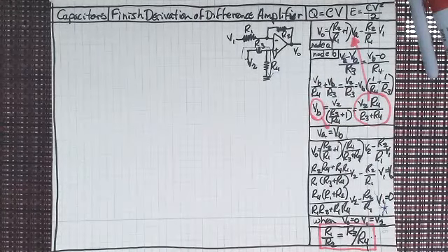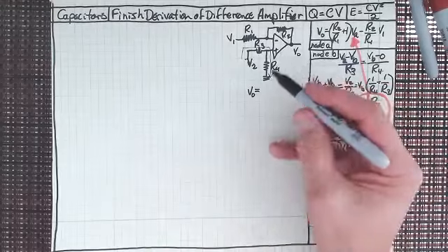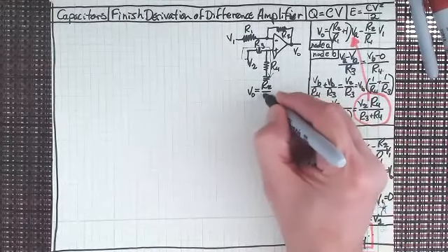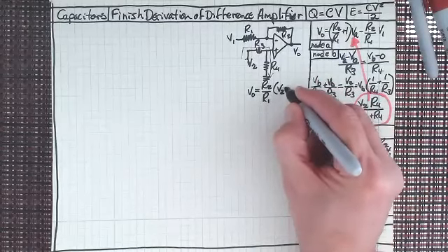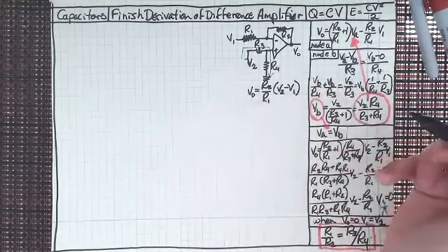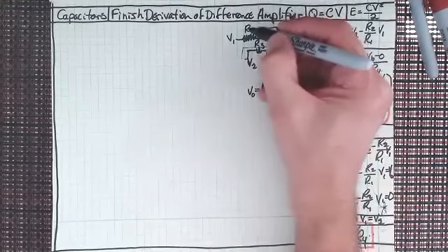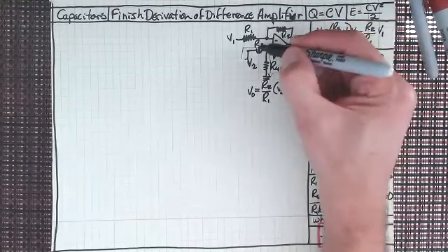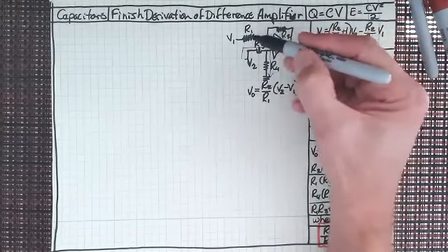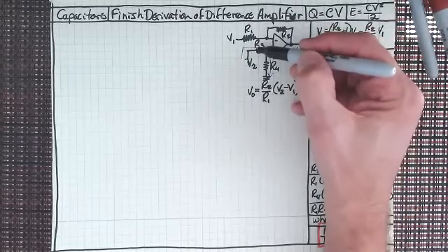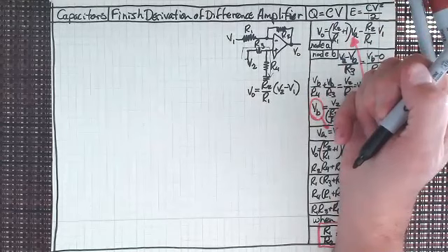Now, what we end up getting out if we use that identity is our equation that says that V out equals R2 over R1 times V2 minus V1, right? Now, if R2 and R1 are 1,000 ohms and 1,000 ohms, and the other two are 10,000 ohms and 10,000 ohms, because it's just the ratio that we're looking at, I could use a 1,000 ohm and a 1,000 ohm here. I could use a 1,500 ohm and a 1,500 ohm here. It would still work out fine, right?